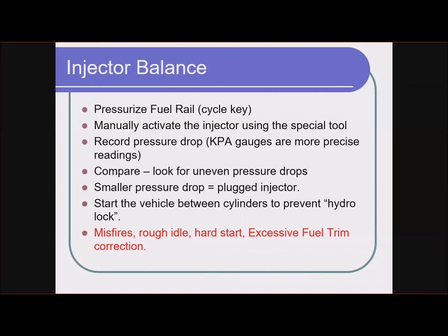An instructor was doing a demo with the Ford scan tool, and the Ford scan tool just runs through and automates it. It's kind of nice. It fires each injector, then it repressurizes the fuel rail, then it fires the next injector, then it repressurizes and fires the next injector, and it just runs through an 8-cylinder engine in less than a minute. They're all done automatically. It controls the injector firing.